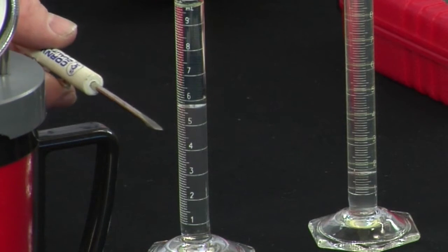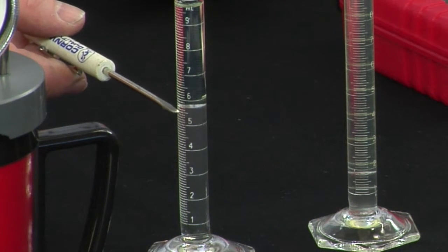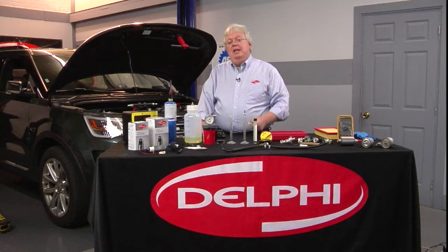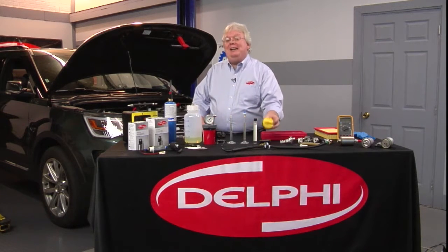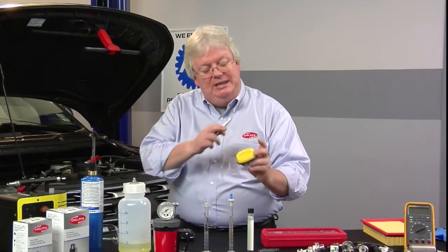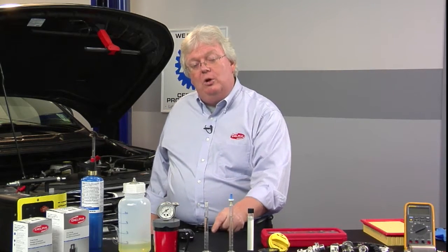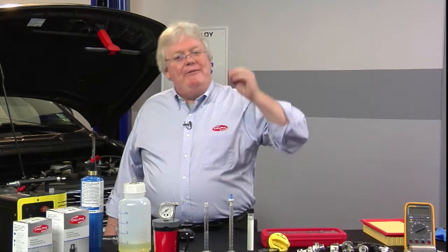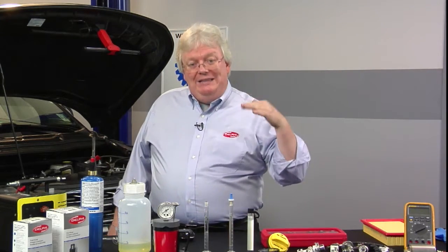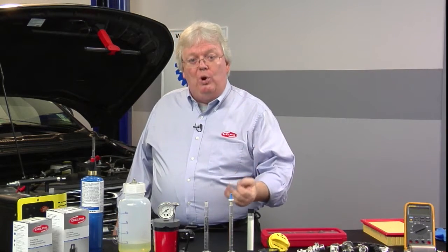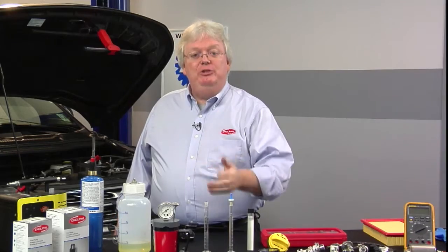Here it's almost up to about 55 or 60, so this is about E50 or 60. This is a very high alcohol content with the separation line clear up here, indicating we have an issue. If it doesn't say flex fuel on the filler neck, doesn't have a yellow cap like this that says E85, then if you have a sample like this drawn from your customer's vehicle, you have your answer to why fuel trims are raising positive numbers, compensating for a very energy poor gasoline and also giving you drivability problems.